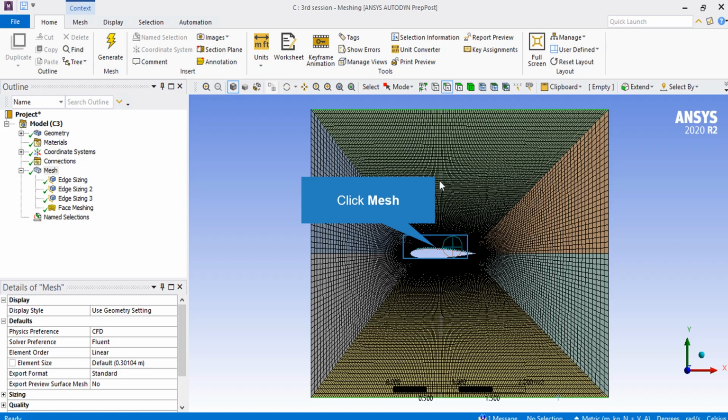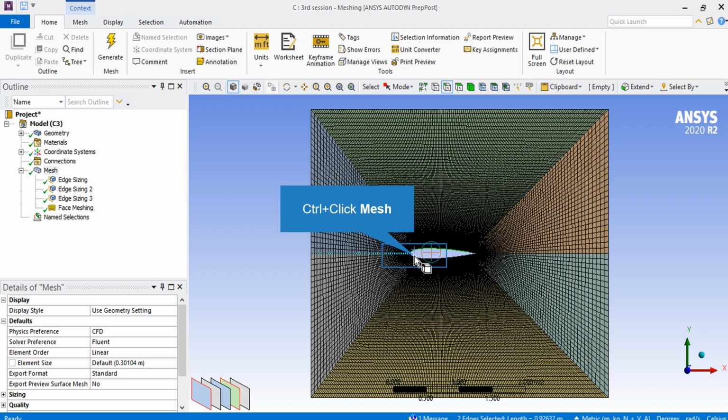And for the final part, we select the outer edges of our airfoil to be our wall boundary. We also select all the faces of our geometry and we set the name of flow for them. After that, we exit the ANSYS meshing software and launch the Fluent software.